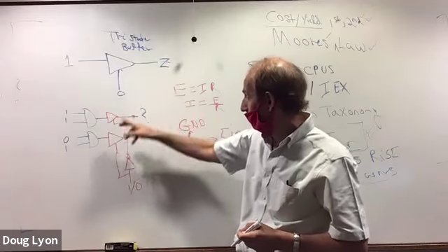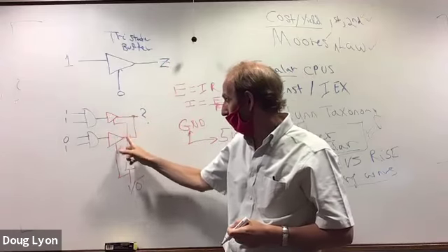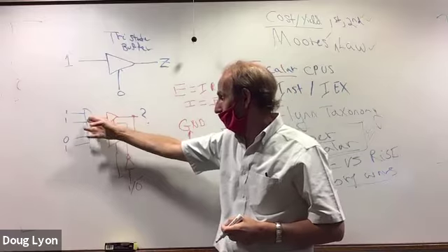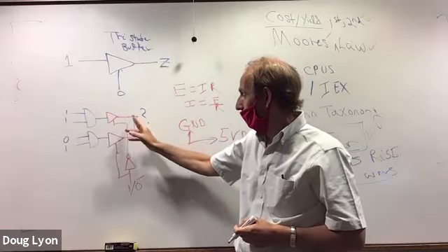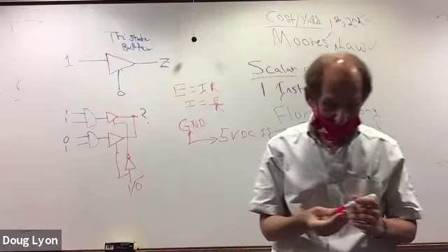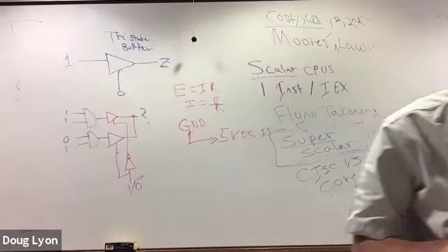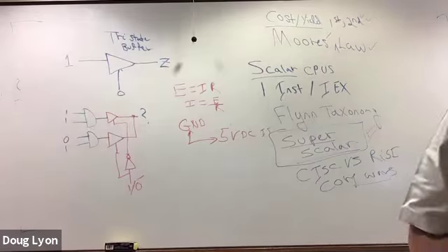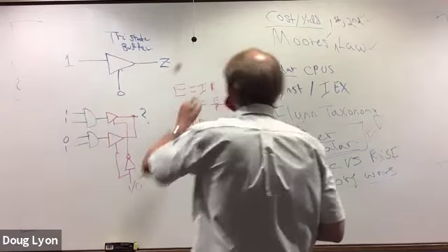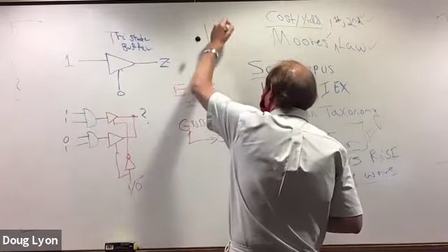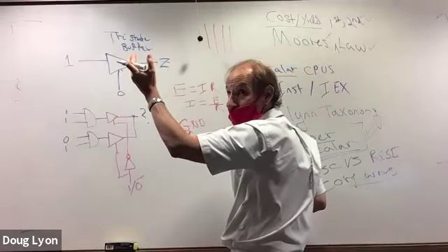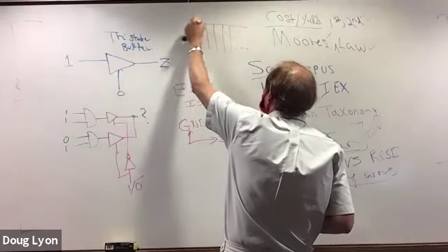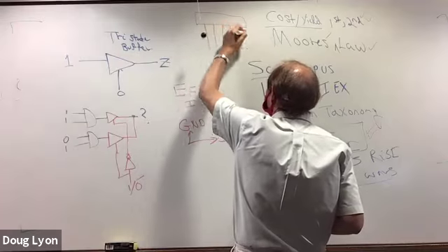And that high impedance state means the output will not reach the other side, and therefore this will be the dominant AND gate. You need these things, because otherwise you can't have what's called a bus. The bus consists of, I don't know, make up a number, 64 wires, 32 wires, whatever, and it's being driven by multiple cards that are plugged into the bus.